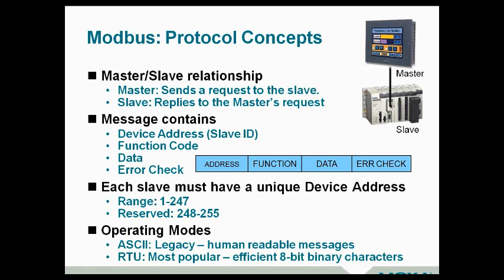correspondence here. If you take a look at this on the upper right-hand corner of the screen, you can see a little bit about how this works with both the master and the slave. In this case, we're showcasing that with an HMI being the device that's requesting data as a master from the slave, which in this case is the PLC. So again, masters ask for information, and the slave says, okay, here's what you asked for, here's that data.